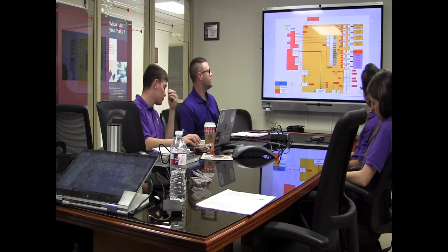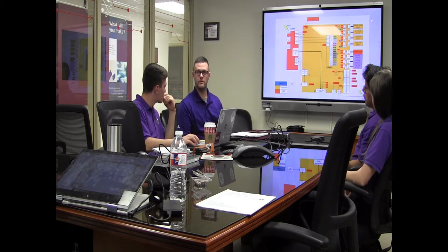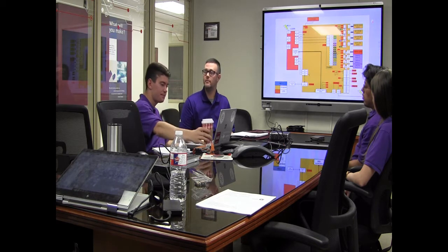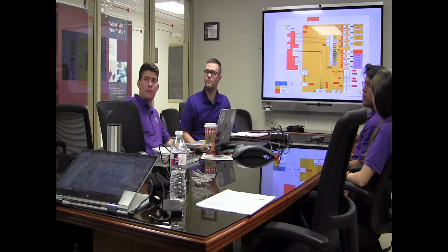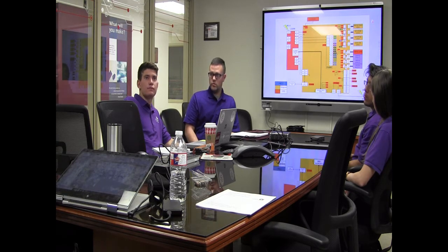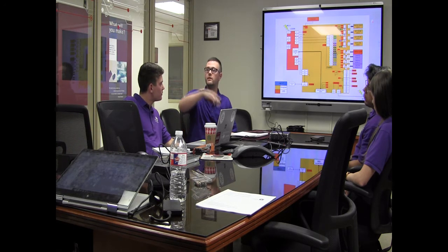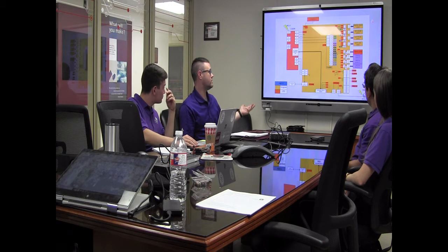So a little bit more detail on this screen. Basically, the key part is that all of our unused LaunchPad I/O, we just crank out to a 40 pin male IDE I/O fan out, just a standard, like what used to be on an old hard drive connector. And have those signals been verified? They are continuous. We don't have anything hooked up to them, so the only thing we know is a pin on the 3200 is on a pin on the connector. Exactly. As well as pass directly through, just as per the LaunchPad standard, so you can keep stacking stuff until you get tired. Additionally, we have lots of grounds on that, as well as 12 volts, 5 volts and 3.3 volts. So if you want to put a long cable on that and start connecting stuff, you probably could.